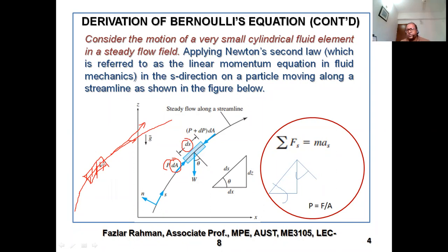That force is the pressure force of the fluid. So pressure over here is working on the fluid. And obviously, if it moves upward, over here the pressure is low. That's why it is moving upward. So I am taking the pressure on the left side as P. So what will be the pressure on the right side? On the right side, I am taking P minus dP. That's why it is moving upward, right? Now, for simplicity, instead of P minus dP, I can say P plus dP. What I'd like to say is that the pressure at the two ends is not the same. There is a pressure difference, and due to that pressure difference, the fluid is moving. That means after derivation, this dP might come out negative.